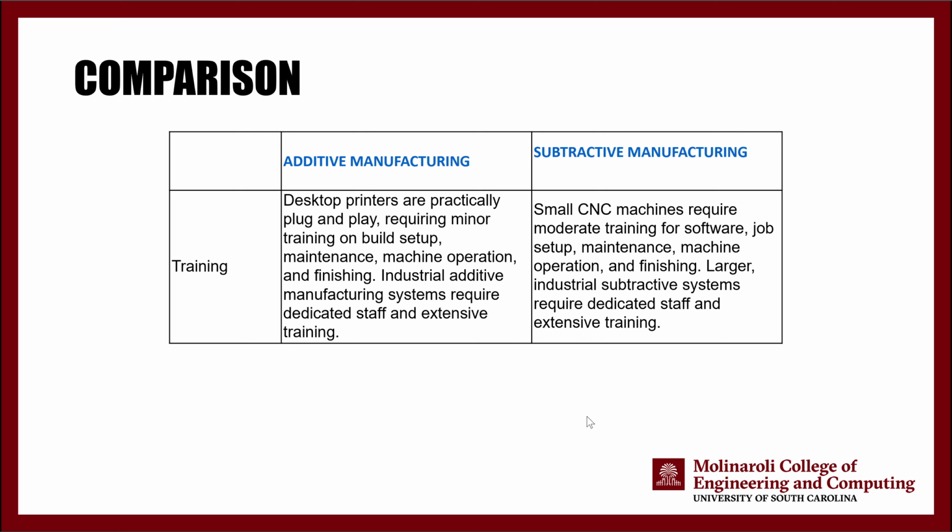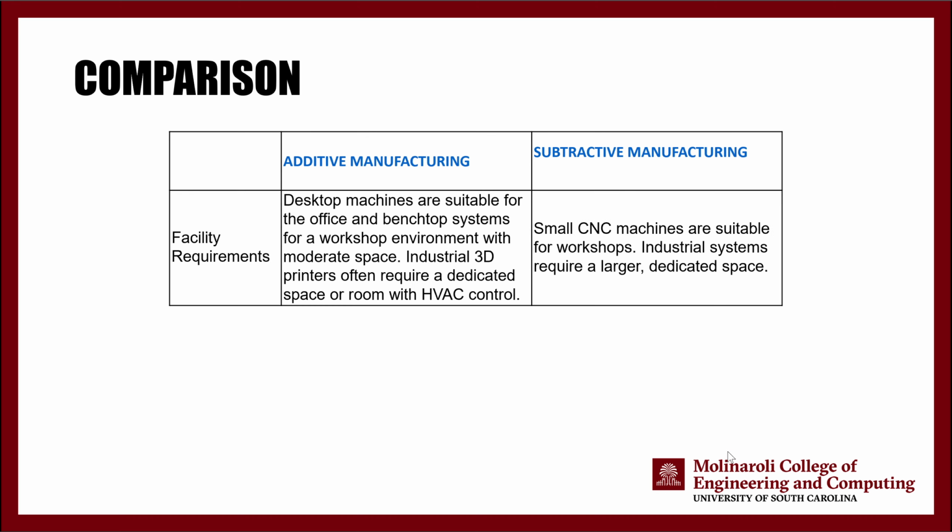Then training wise, additive manufacturing 3D printers are usually plug and play. As long as you know how to create a CAD model, you can use the slicing software that comes with the 3D printers, print your material, and be done with it. On the other hand, CNC machines usually require a little bit of training, maintenance, and jobs, so more than 3D printers. So additive manufacturing training wise is going to cost us a little bit less.